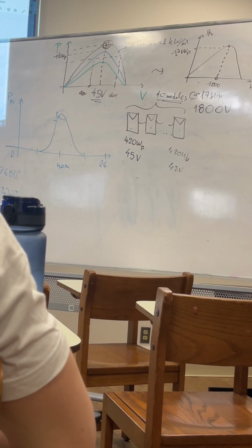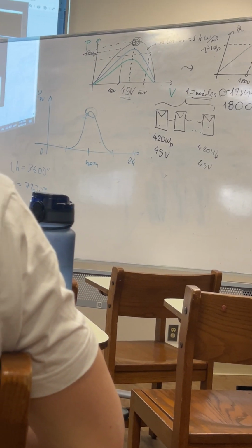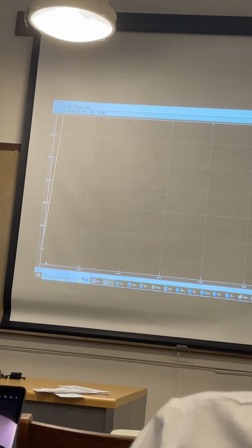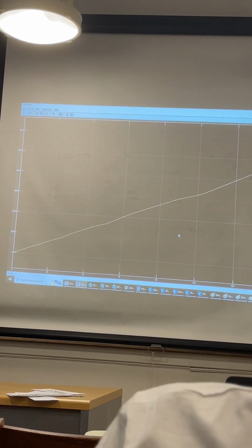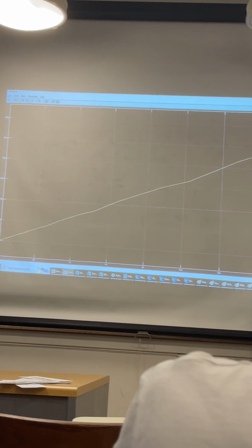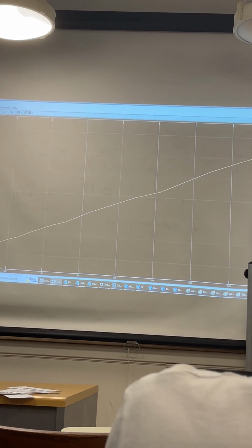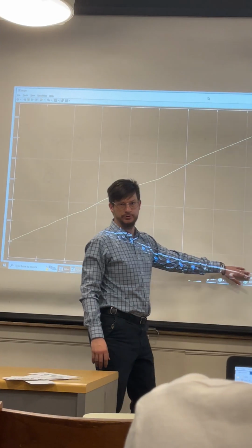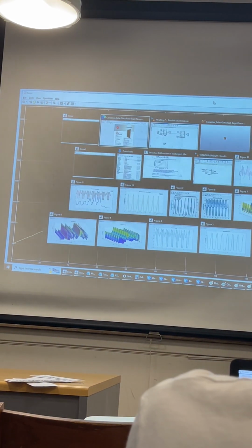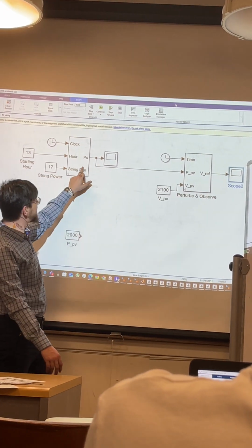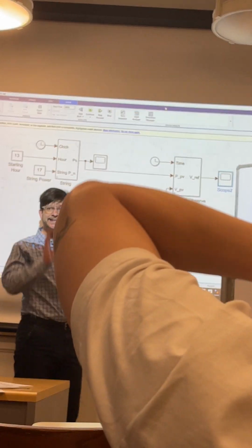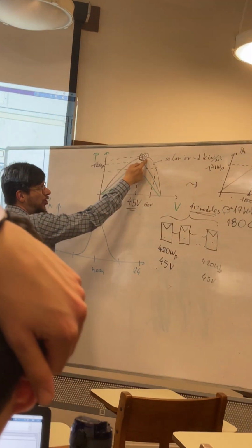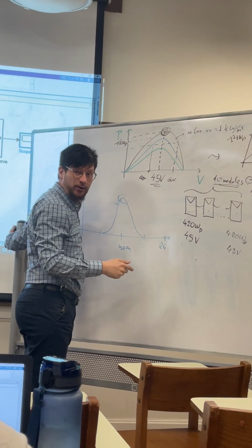So that's why, when I pause this simulation here, let me do something, it is not too difficult to fix this. Alright, better centered now. In the first few hundred seconds of the operation, the perturb and observe takes in the input of the photovoltaic module and starts to impose a slowly increasing voltage so as to cause the corresponding increase of the output power.